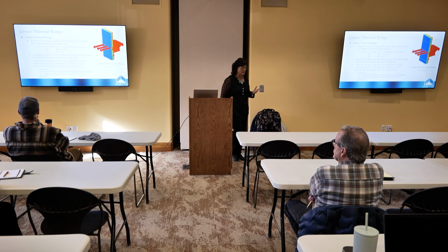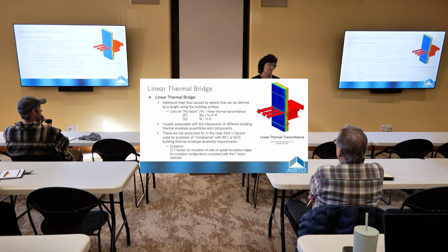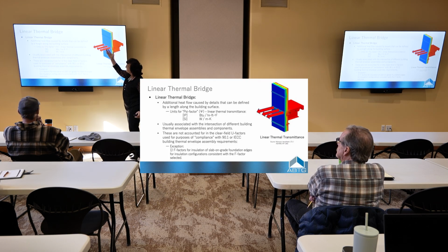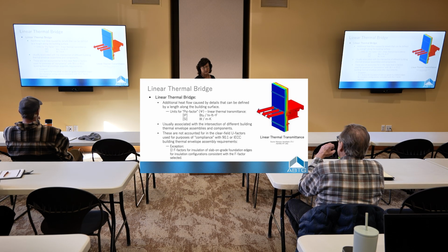There are a lot of different kinds of thermal bridges. A field thermal bridge is something of the whole thing, like maybe those Z panels that would affect the thermal bridging of the whole wall. There's linear, like at floors or decks or patios or something like that, and then you have point thermal bridges.